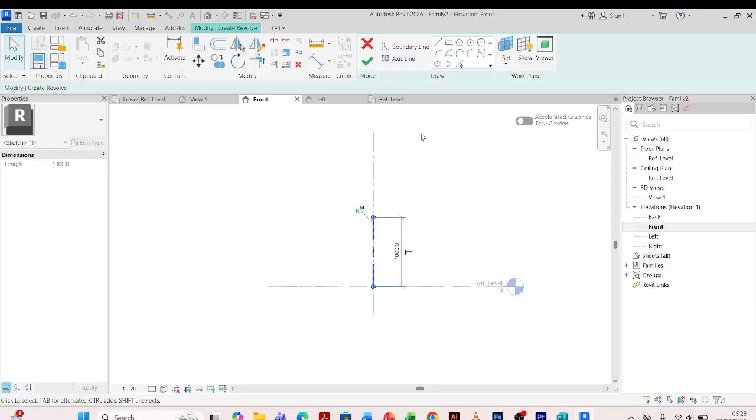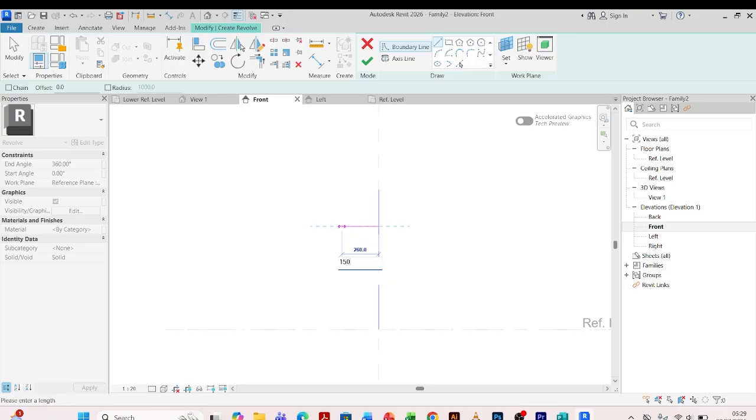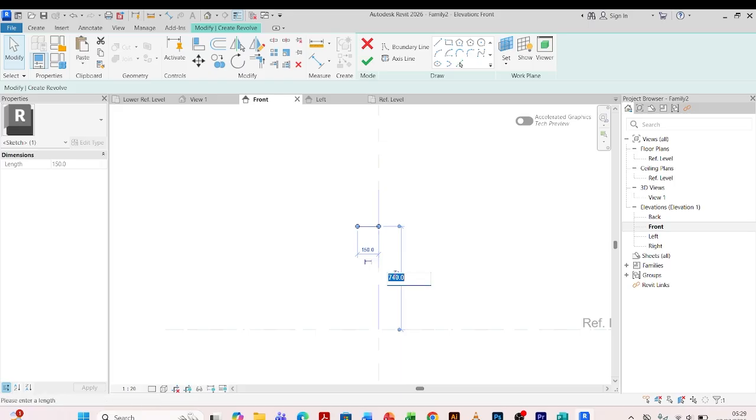It's not supposed to be so high. I'll first turn off the true line white. Then after the axis line, I'll go to boundary line and draw it here. I'm going to have a base of 300, so I'll make this 150. Enter. Then for the height, let me give this maybe 300.